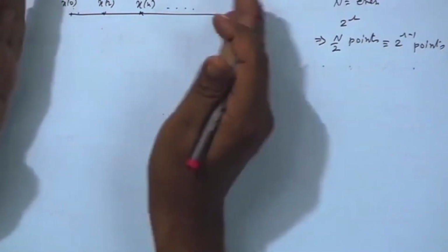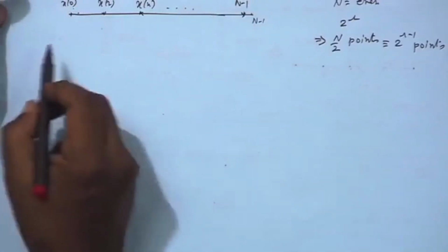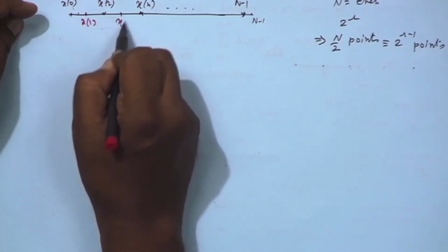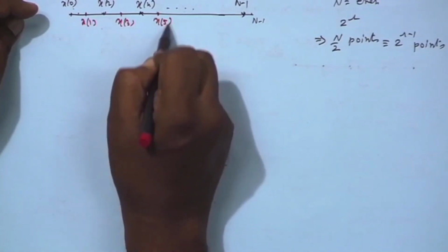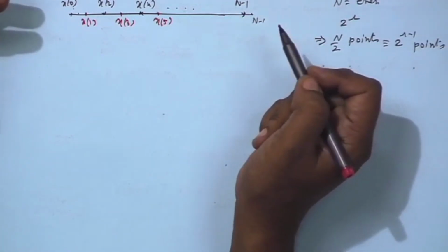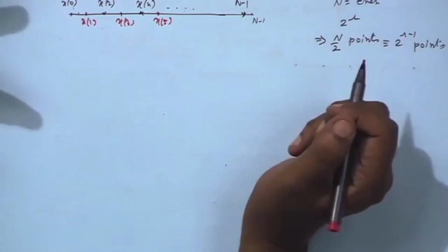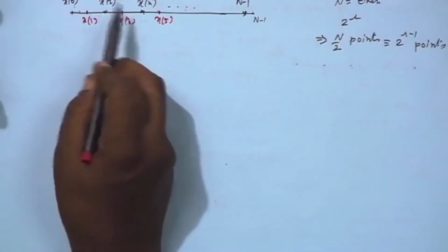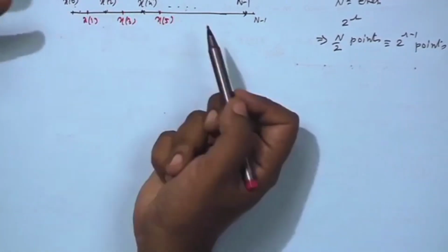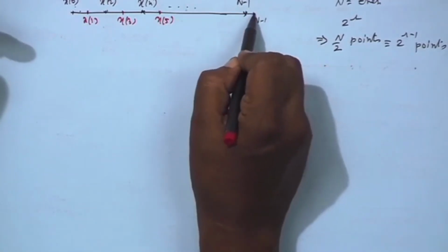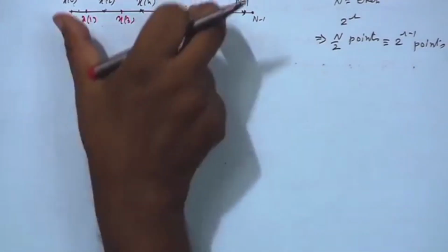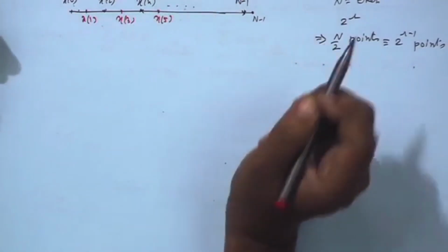And so, I take those points out, form one set, and I take x1, x3, x5 dot dot dot; these are like the polyphase factors. You are basically doing polyphase decomposition by 2. The 0th polyphase component is x0, x2, x4 dot dot dot, and the first polyphase component is x1, x3, x5. Just that. In those good old days of FFT, polyphase decomposition did not come up, so they wrote even part and odd part. But now you know polyphase decomposition.